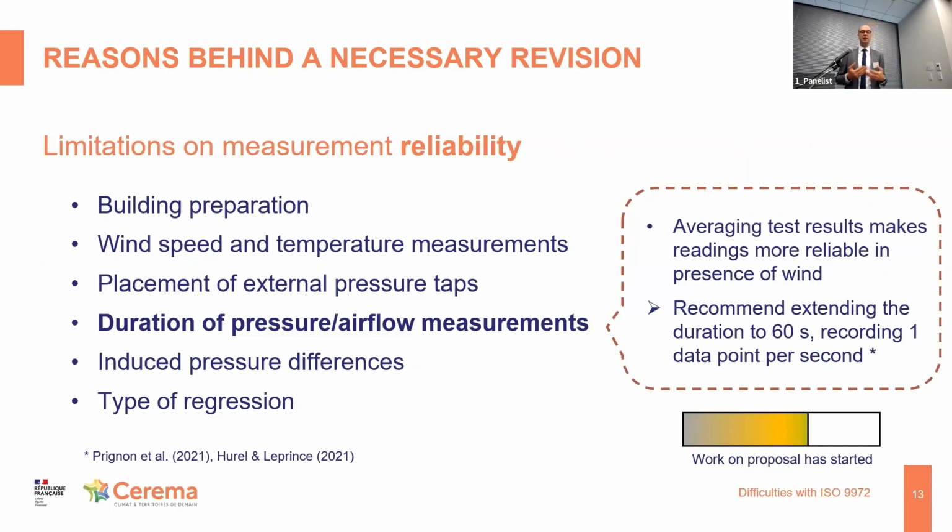Next, there's the duration of the pressure measurement and airflow. In this, the standard says that, at least for the zero flow pressure measurements, the measurement should be averaged over 30 seconds or more. But this really influences the reliability of the results, especially in the presence of wind. So we recommend to do it for at least 60 seconds or to adapt it according to the variability of the wind speed, for example, for the zero flow pressure measurement.